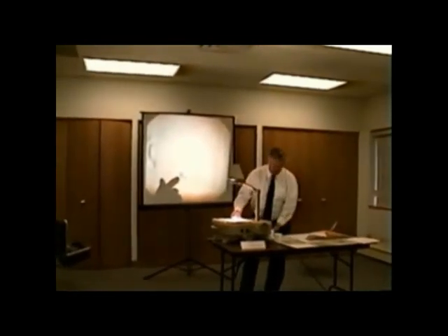and look at this temperature rise. And again, we're only using this as an example. So let's see. Let's just say, for an example, that this came from the factory on a heating speed, which is question 5. It came on medium-low. And if we wanted to increase the temperature rise, what do we do? Slow the blower. Lower the blower, correct.